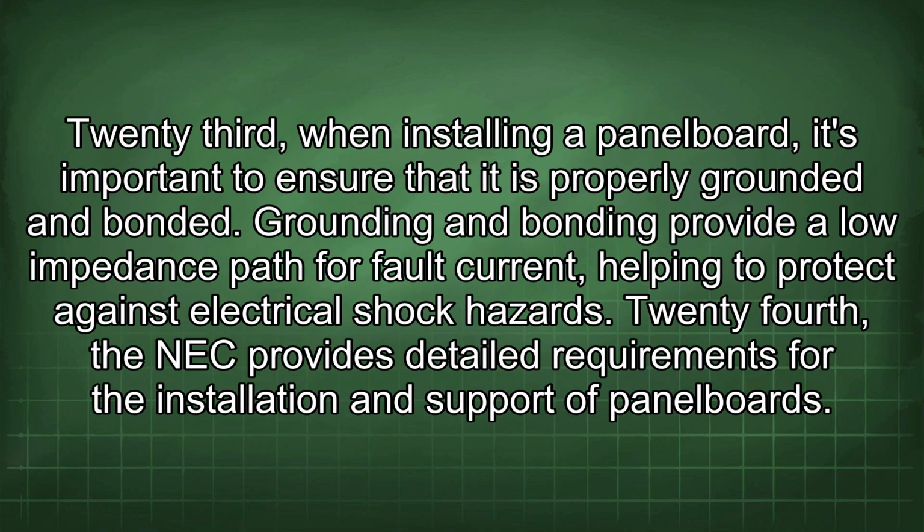23rd, when installing a panel board, it's important to ensure that it is properly grounded and bonded. Grounding and bonding provide a low impedance path for fault current, helping to protect against electrical shock hazards.